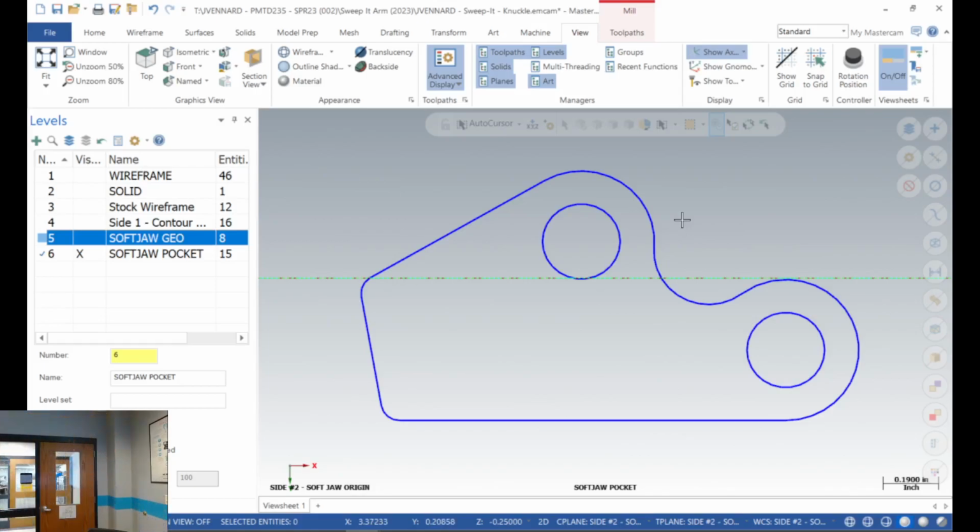This is a good example of it. If these were in the vise, you wouldn't be able to open the vise. Like right now you can because everything's real loose, but you wouldn't be able to open the vise because it has an undercut here that they machined back into it, and it's locked. The part's locked in there. We don't want it to be locked in there. Pass those around.